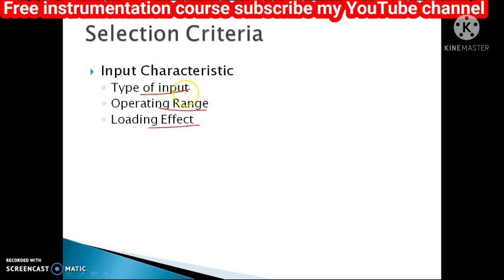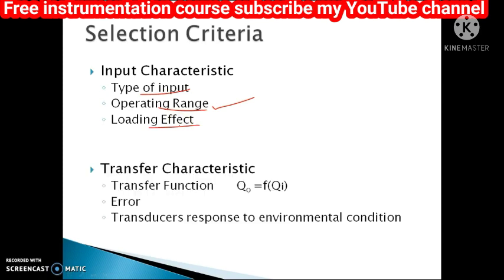Once we know the input quantity, the range, how much it will vary, is very important for the choice of the transducer, which is determined by the operating range. The maximum limit decides the transducer's capability while the lower limit determines the error. The last is the loading effect. That is, the use of the transducer should not affect the input quantity being measured.